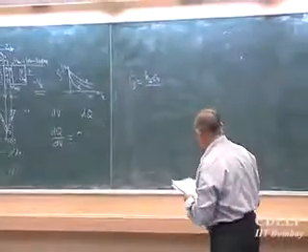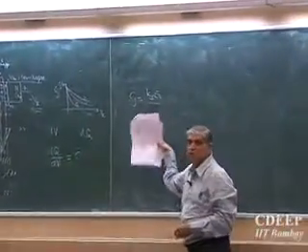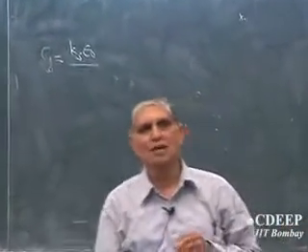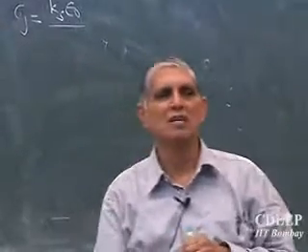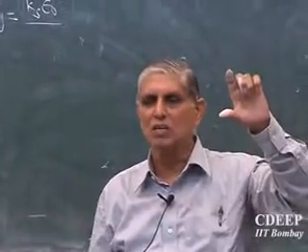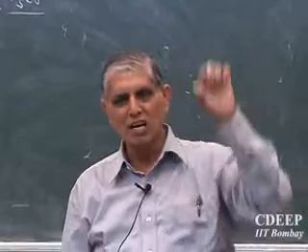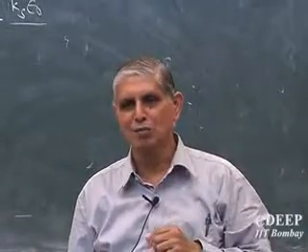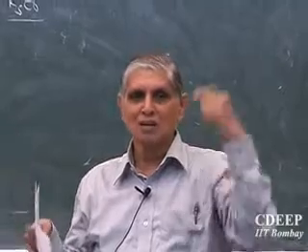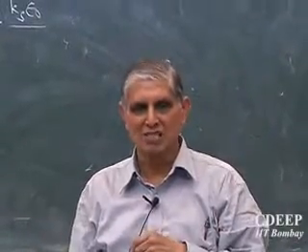Okay, so let's say I am writing per unit area in all capacitance unless said otherwise. We use capacitance per unit area. Why? Because area is something device people finally will tell you how much current I want. So that area is decided not by just capacitance but also by current, because you will calculate current density there also. You will multiply by area to get your currents or power.